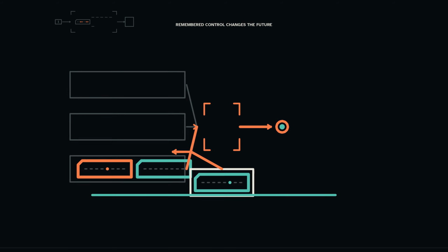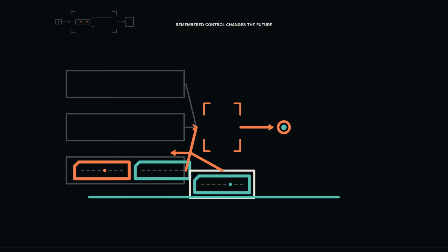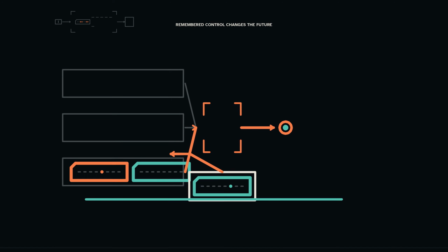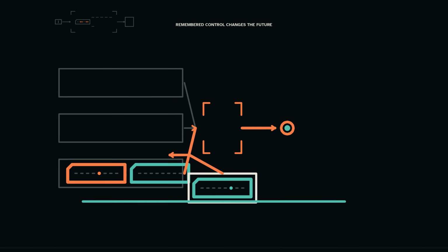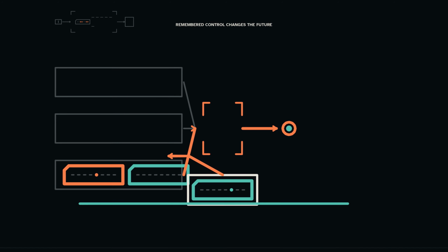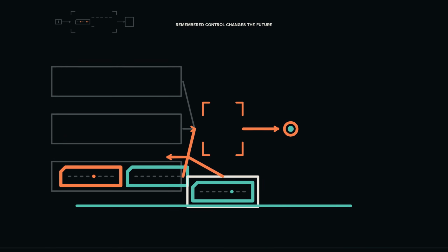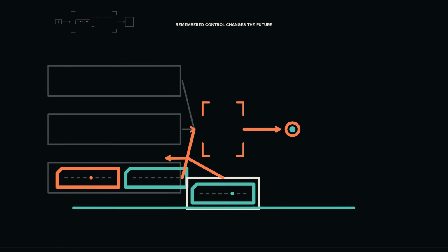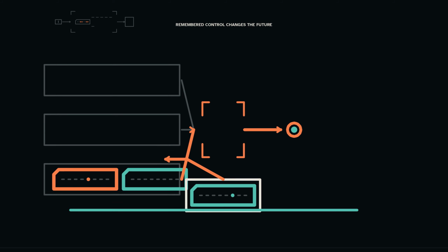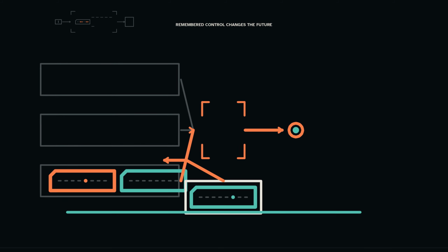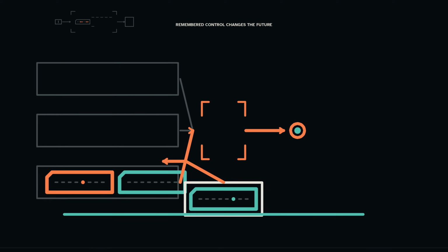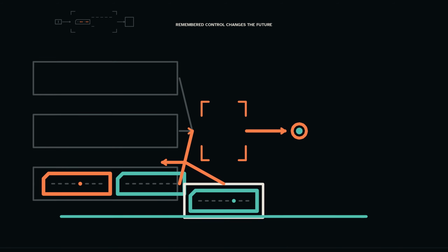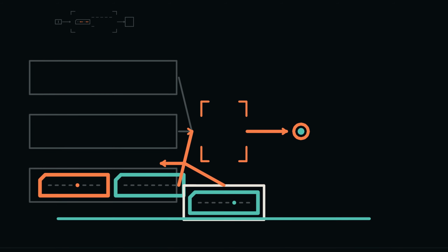Suppose PC begins at hexadecimal 20 and every SE8 instruction occupies 2 bytes before a jump, which addresses follow, hexadecimal 20, 22, 24, and 26. PC advances through both bytes, so the ordinary next address is the start plus 2. An odd target is illegal because it would begin inside a pair. This 2-byte rule belongs to SE8, not every instruction set.